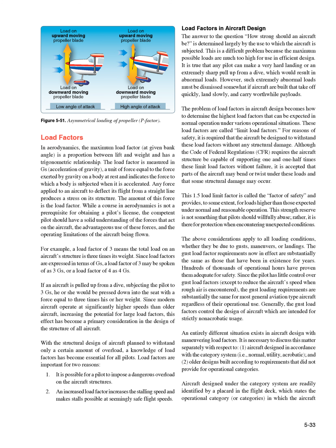For reasons of safety, it is required that the aircraft be designed to withstand these load factors without any structural damage. Although the Code of Federal Regulations, CFR, requires the aircraft structure be capable of supporting 1 1/2 times these limit load factors without failure, it is accepted that parts of the aircraft may bend or twist under these loads and that some structural damage may occur. This 1.5 load limit factor is called the factor of safety and provides, to some extent, for loads higher than those expected under normal and reasonable operation.